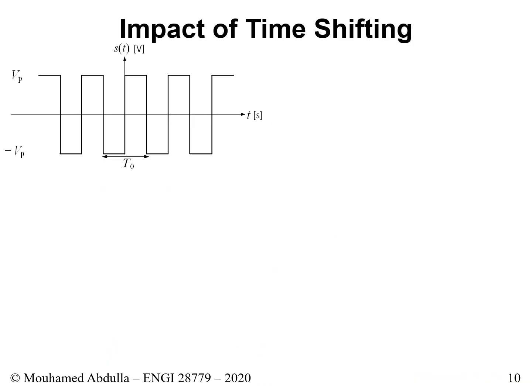On the previous slide, we saw the impact of the DC offset. Basically, we learned the impact that a DC offset has on the frequency domain of a signal. We realized that you'll just end up having the signal as it was before, except now you will have a spike at frequency 0. It's just DC, so there's no frequency, and therefore you'll have a spike at frequency 0. And we figured out how to assess the value of this DC component. At this point, we ask ourselves, what if now we want to shift in the time domain?